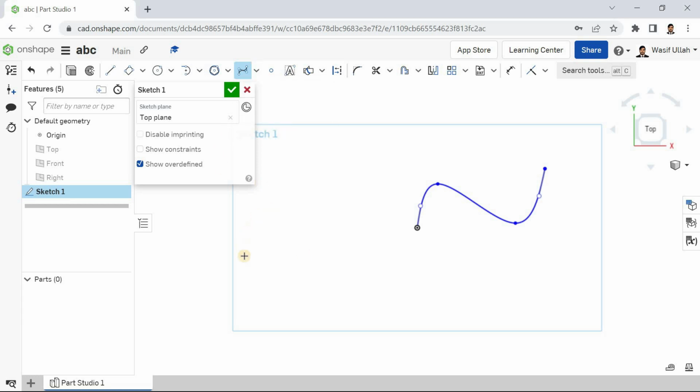Next we have the bezier. In this case, where you click it just defines a bezier curve along with the spline. Like when I press escape, this is my actual spline and this is my bezier curve, because I just clicked here, then here, and then here. The next option defines a spline control point.